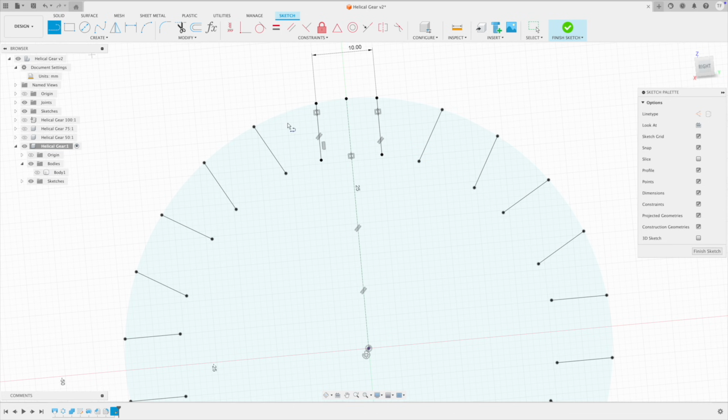Do you know what we can do? Yeah, just to make it easier on us, let's go back in time. We can create that line. We can create another line from there to there, and we actually want these two lines to be parallel with each other. Now this line right here is what we want to dimension or constrain. So this is going to be our 36 mil as our drawing says. So that looks really good.